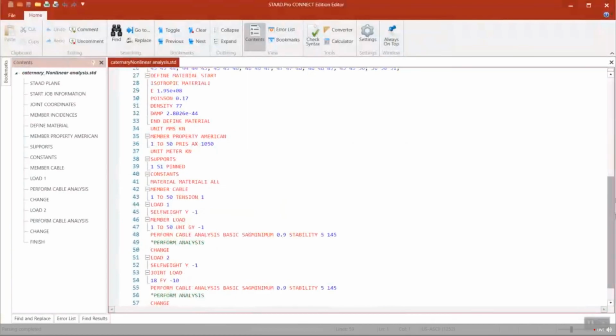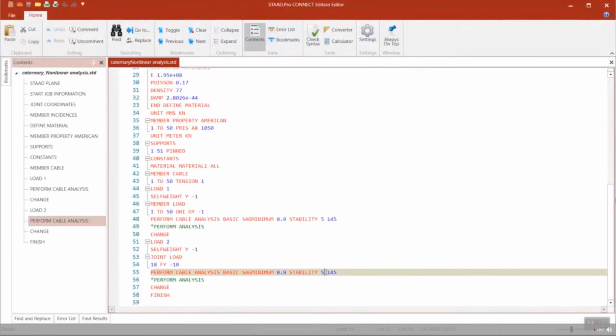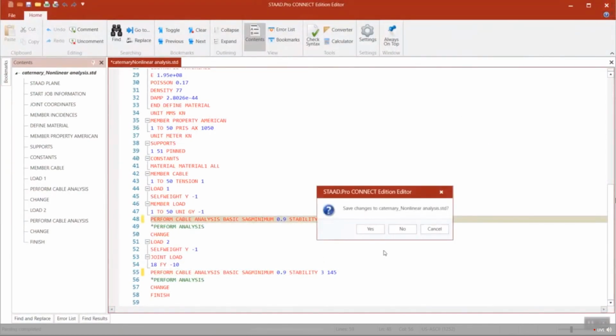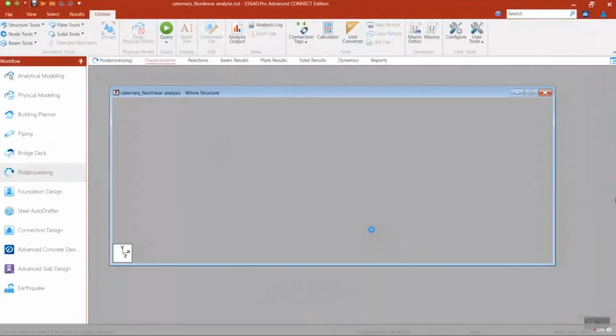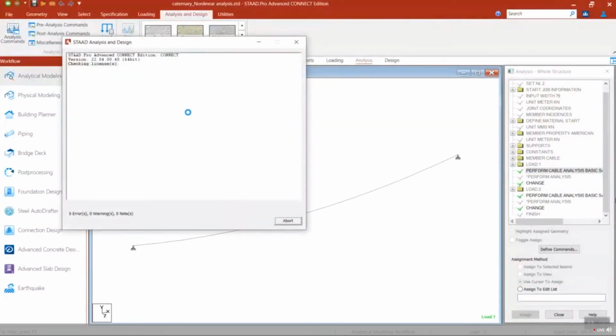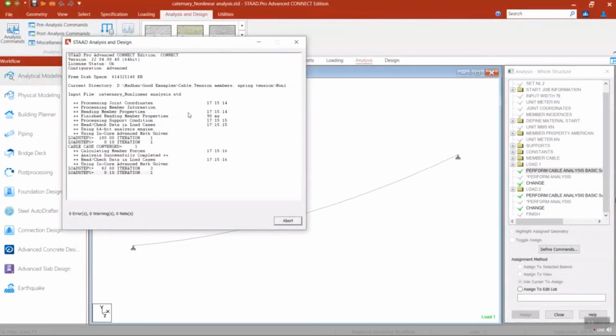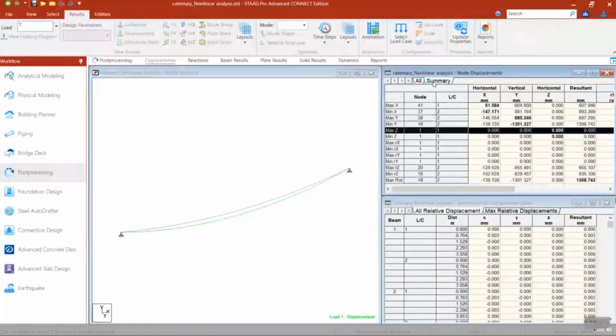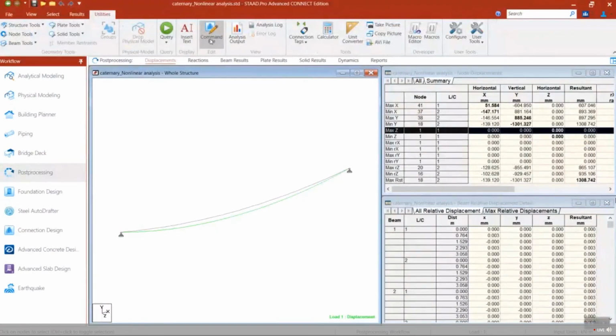So this is how you iterate. You do trial and error to get the correct solution for your model. You can see the cable case converged. So I'm doing it the reverse way. Initially I used a value of 1, and then I used 10, and then 5, and now reduced it to 3. You can also go the other way, from 0.1, 1, and then 2 and 3. So there are multiple solutions. You can see that now I reduce it to 2.